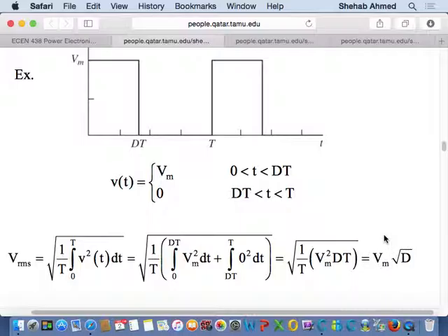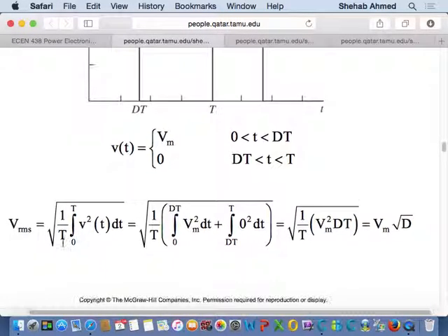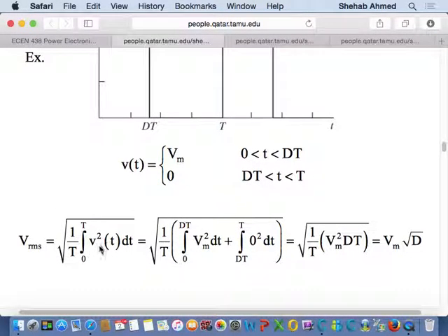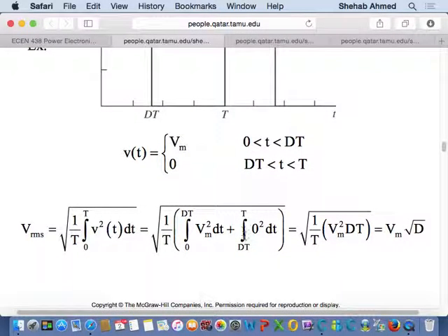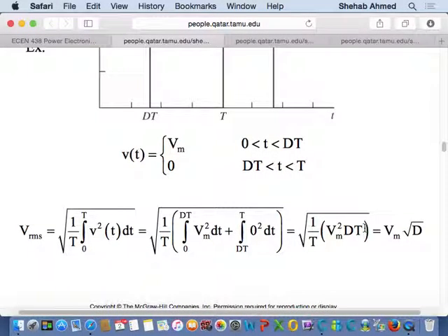So you will see waveforms of pulse square waves, for example, and you will ask, okay, what's the RMS value? It's an equation, or you can go through, of course, the integration. You go through the integration by squaring the waveform, finding its average value, putting everything under the square root, and then they go through the integration for you here. But it's something like the Vmax over square root of 2 thing for the sine wave.